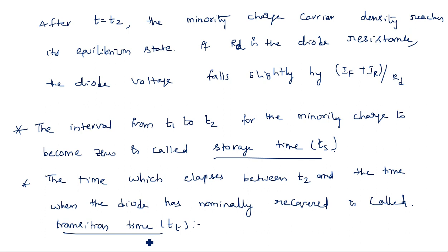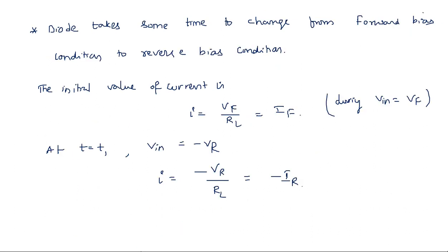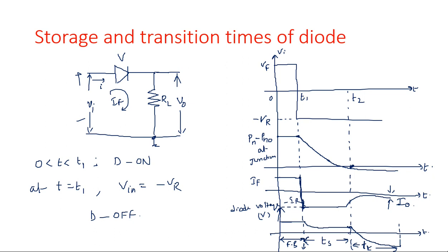So the reverse recovery interval will be completed when the minority carriers which are at the same distance from the junction have diffused to the junction. If you want to get back the same situation, after this time period, if you give the positive supply Vf again, after some time it comes back. This is the storage time and transition time of the diode. Immediately they will not change.